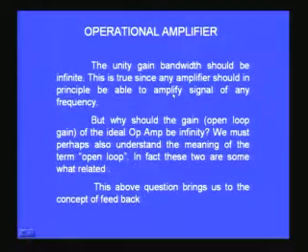We want amplifiers which will amplify all signals irrespective of the frequency, whether low frequency or high frequency, by the same magnitude of gain. It is always very difficult to realize such amplifiers; we all know that every amplifier will have a finite bandwidth. So in principle ideally we should have infinite bandwidth, understood. But why should the gain of an ideal operational amplifier be infinity? Or why should a typical operational amplifier have a very large gain, 100,000, why not less?